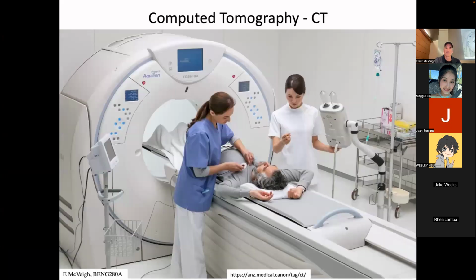So here's the scanner. Okay, we're pretty familiar with it now. There's a tube in here, there's a detector over here. Both those things spin around at high velocity, now greater than 4 times a second. That means the electronics in there sustain like 80 Gs, right? So you have to tighten your bolts to get that thing to behave well.